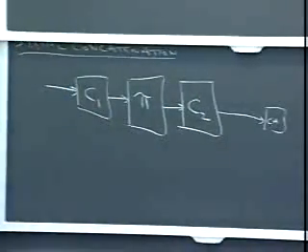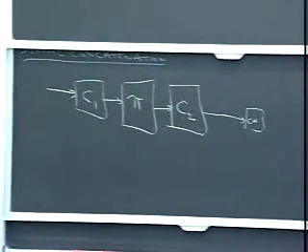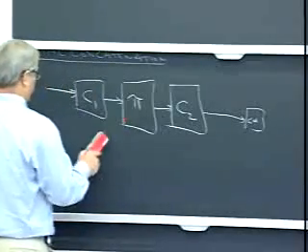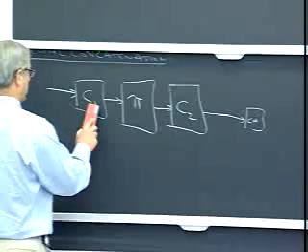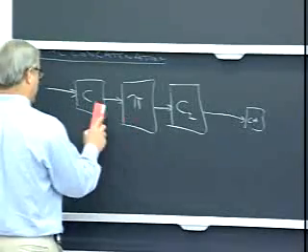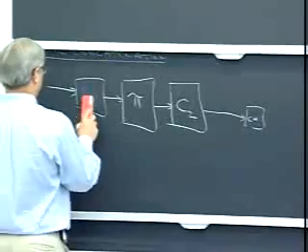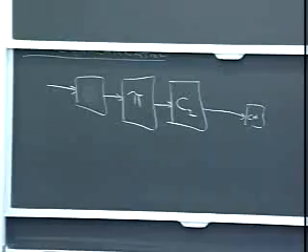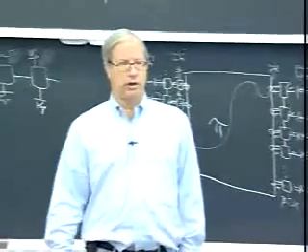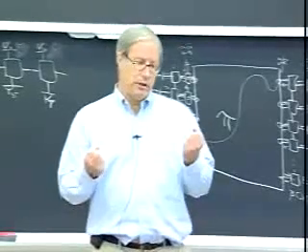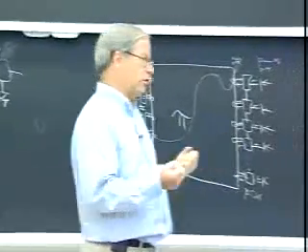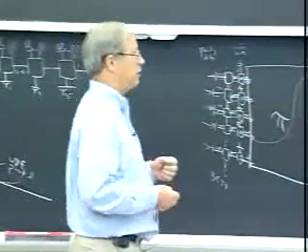And so that's the context in which concatenated codes were originally invented, and that's the way they're used on the space channel, for instance, the additive white Gaussian noise channel. But here we're talking about the same block diagram, but much simpler codes. And again, the idea is to build a big code using very simple component codes, which is what we did in low-density parity check codes. That's a big code built up basically out of zero-sum and repetition codes. A turbo code is a code built up out of two simple convolutional codes.